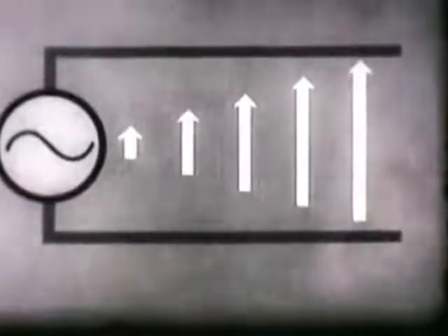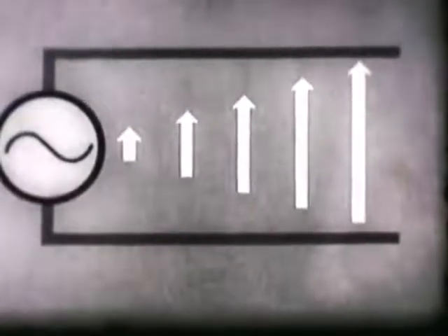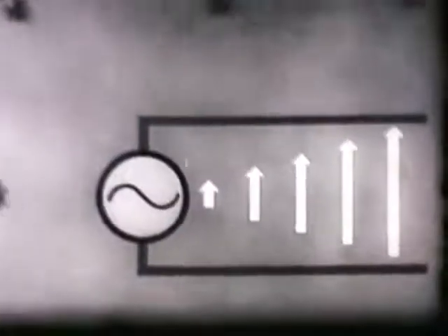What can we do about this? Well, the same quarter-wave transmission line holds a few more tricks up its insulation. When only one wire is moved perpendicular to the other, the closed electric field which existed between the upper and lower conductor becomes a partially open field.